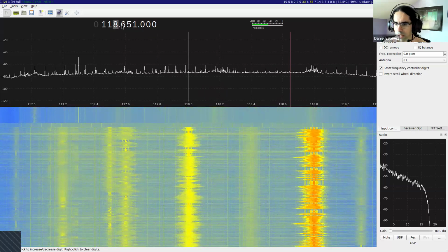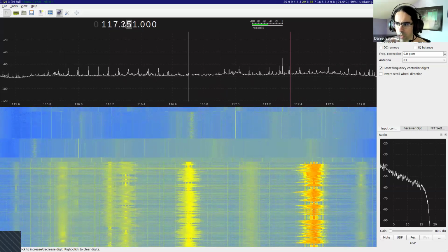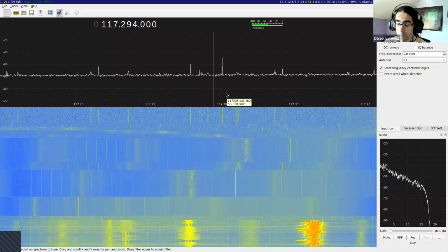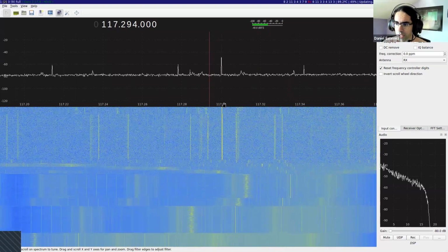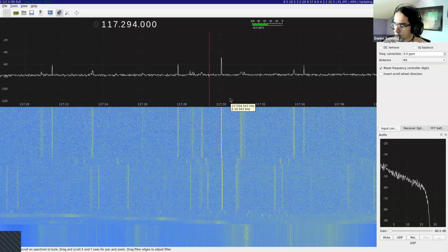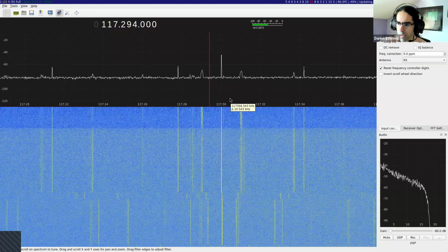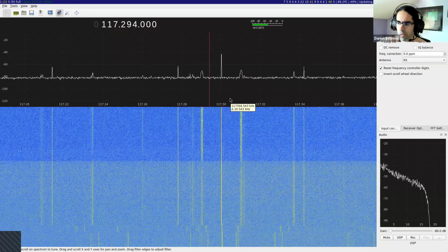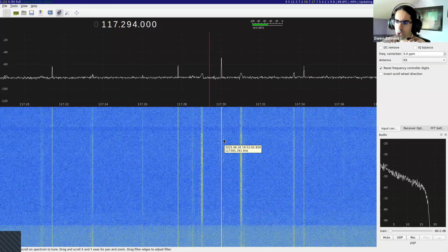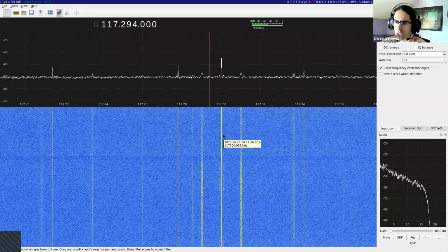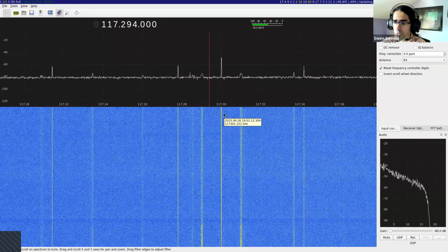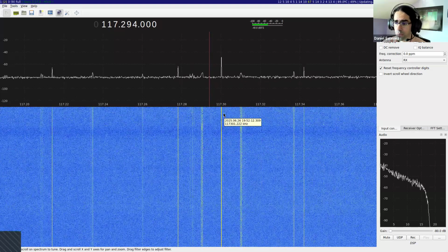But for example, if I tune to 117.300, I know that in here, where I'm living, there is an aircraft navigation signal, and the signal is this thing, and it also has these things. Maybe, if I put it up in the air, you can see it better. And you can see also in here, there's some Morse code, which is the identification for the navigation station. That is how an airplane pilot knows that they are tuned to the correct station.